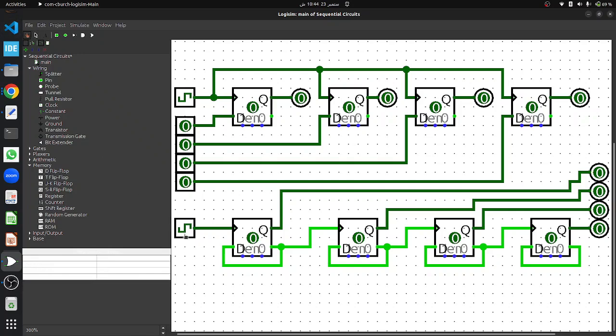Here you can see the clock is at the falling edge. So as soon as we toggle it, you can see the output of the first flip-flop becomes 1. So you can count it like 0, 0, 0, 1. So it is your Q3, Q2, Q1 and Q0. So my counter started incrementing from the count of 1. Let's toggle it back to the falling edge and let's toggle it back to the rising edge. Here you can see the output of the first flop becomes 0 and the output of the second flop becomes 1. This makes the count 0010, which is 2 in decimal.